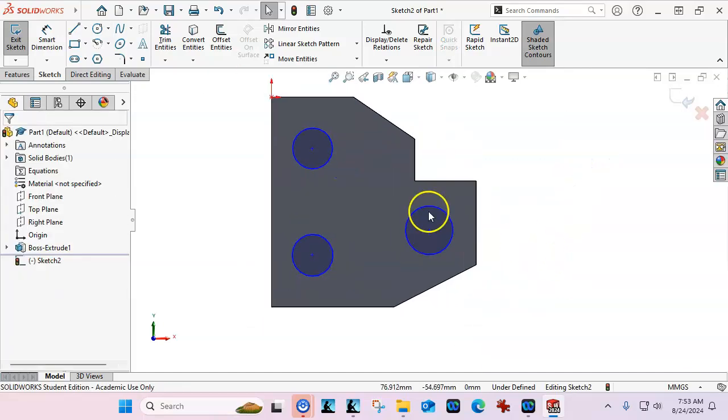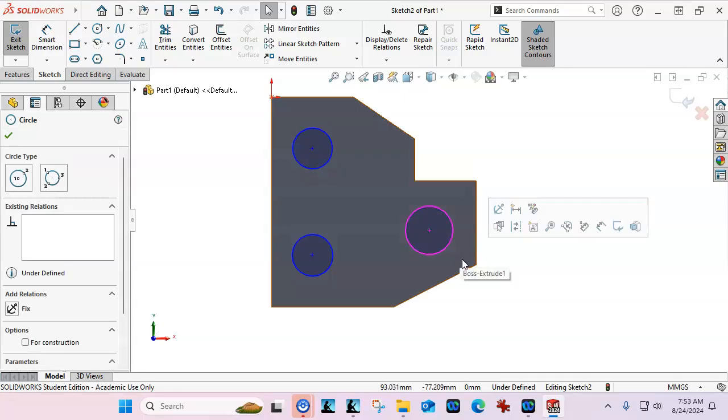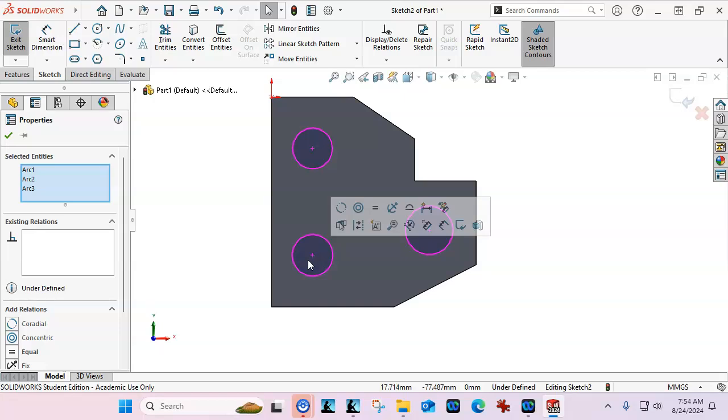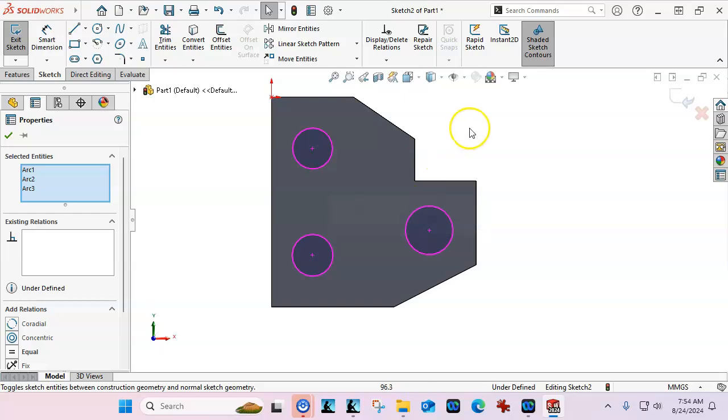All right, so since we're in its own sketch, and I have the three circles, I want to make these equal. We can go ahead and put a few dimensions on it, but the window pick is if I am window crossing. Anything that goes inside of the window from left to right is going to be selected. Window crossing from right to left, anything that is inside or the box crosses over is going to be selected. So a lot of times, just by habit, I'll go right to left unless I'm really thinking that I just want to get a few of those items.